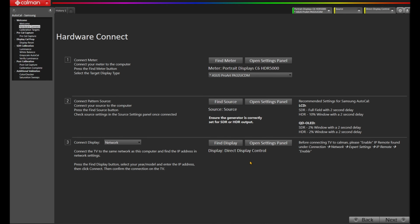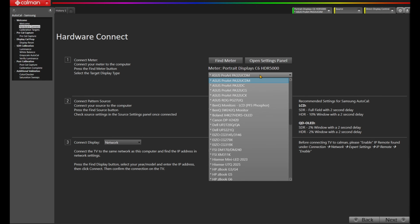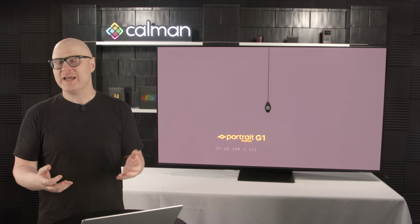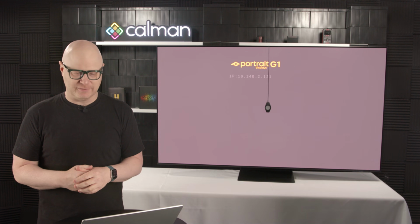Okay, with our C6HDR5000 now connected to Calman, we can choose our meter profile. You'll notice the Asus ProArt PA32UCDM profile happens to be loaded at the moment. I'm going to click on the profile drop-down window and I'm going to search for the profile that best matches the display. And it looks like our team has made a profile for the Samsung S95F, which happens to be what this model is, so I'm going to select that one. For more information about meter profiling and meter profiles, please click the link in the description below.